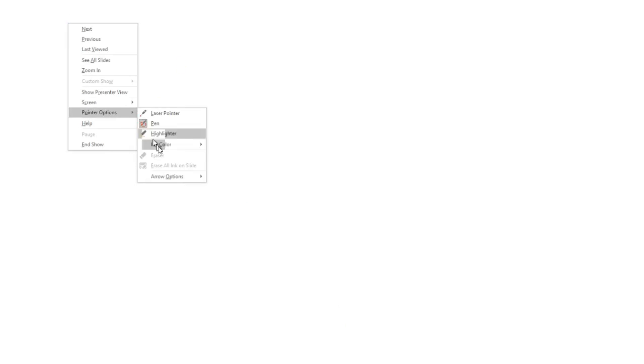So moving along, if we work through this, we will find that this is negative 200 plus or minus 1300. So the average normal stress is negative 200 psi, and the tau max is going to be 1300 psi.